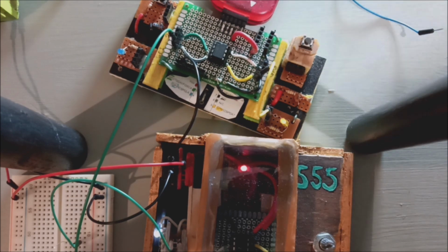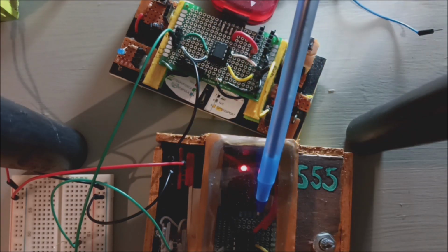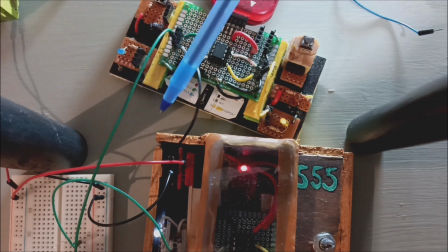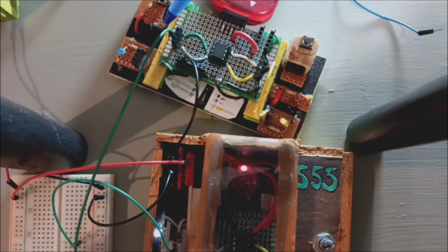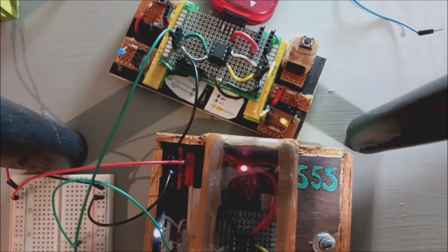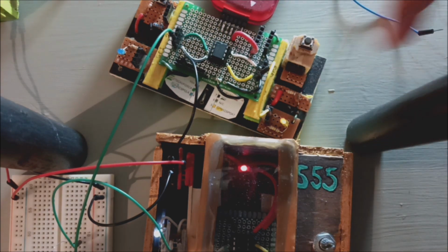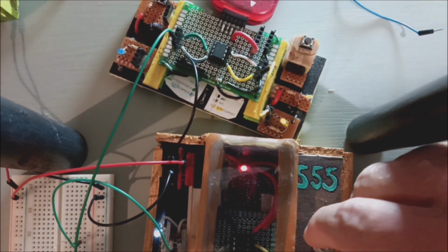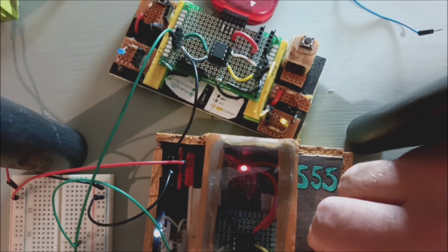So anyway, now there's an output from the 555 timer through the breadboard, through a current limiting resistor into GP1. And once again, GP0 is the output as it's configured in the code. Now the way I had my 555 timers set up, I can adjust the blink rate.